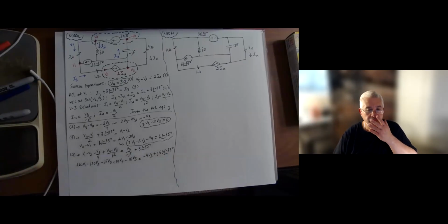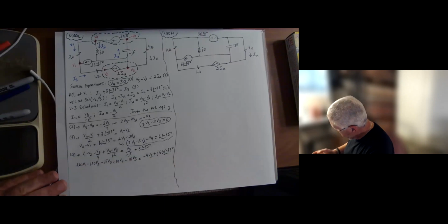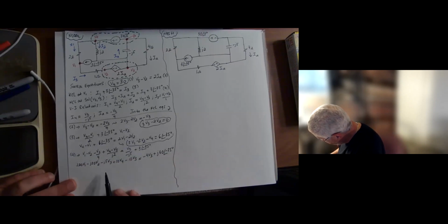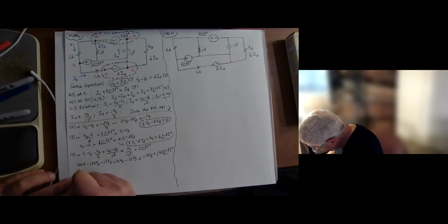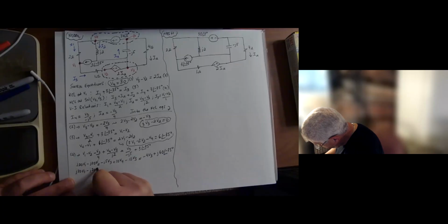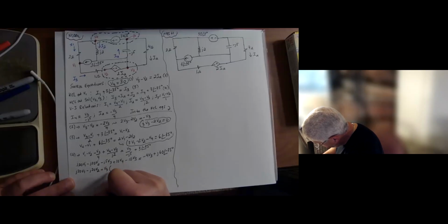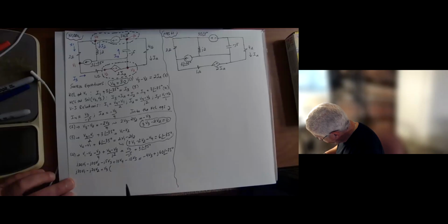Okay. So I can send the minus 4 V3 on the other side here, collect terms. So what do we have? Let me just be careful here to make sure I got my stuff. So I get J20 V1. Do I have V2? Okay, minus J20 V2. And how many V3 I got? So this is going to come plus V3, and it's going to be minus 6 minus J5, okay? And then plus 10 V4.